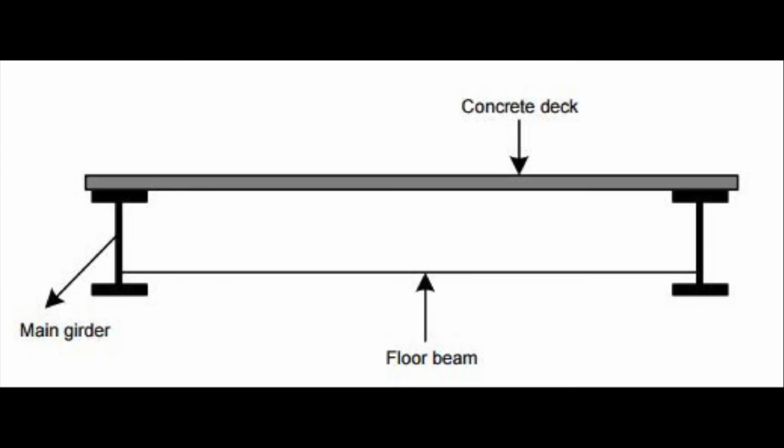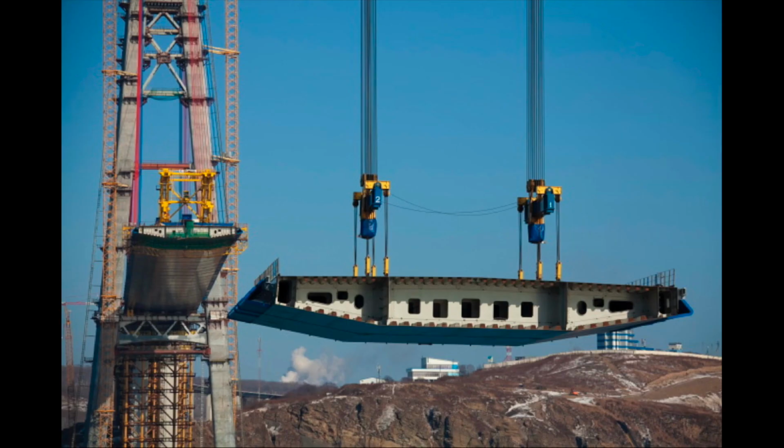This is the cross-section of a typical bridge deck. In this picture, the girders are depicted as I-beams on either end. The cables of the bridge are fastened directly to the girders to support the roadway. The floor beams help to stabilize the girders and keep them a set distance apart. The deck surface lays across the framework, which is made of girders and floor beams. The decking is commonly pre-made into segments so that the bridge can be assembled on-site with minimal effort. This allows for efficient building and repairs.